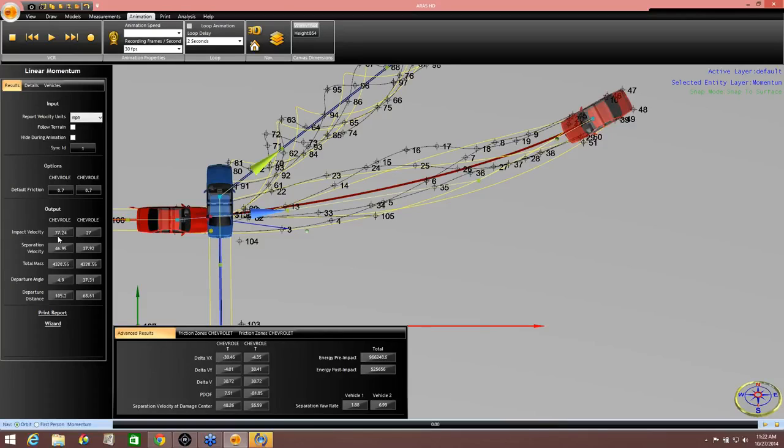So this is the most important and probably most difficult part of any momentum calculation to get right. What did the cars do? And this is where everybody's going to have their own opinion. This is the place you'll get attacked, whether you do this by hand, whether you use a tool, whatever. Because I can assign whatever friction I want there to get whatever speed I want, really. I could do that. But I've got to justify why I use that deceleration rate.